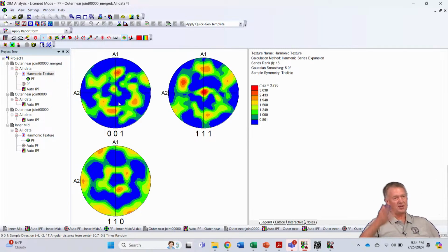All right, so now you've got to think of what's going on. We looked at some modeling a little bit, and we said this is strain energy driven, because of the accommodation strains, right? So we have a hot material, with solidification of stainless going inside and then out, sort of going back and forth with the stainless and the low carbon. And that low carbon is really trying to squeeze down onto the stainless.